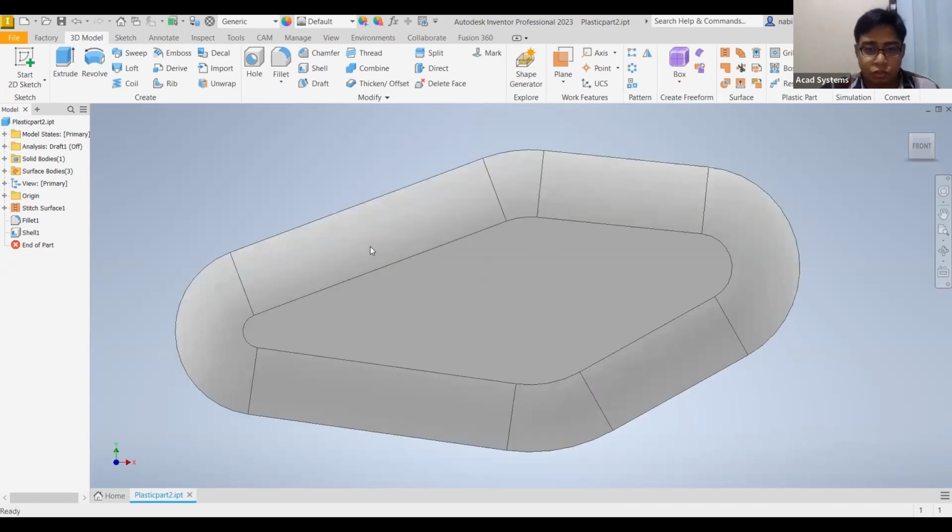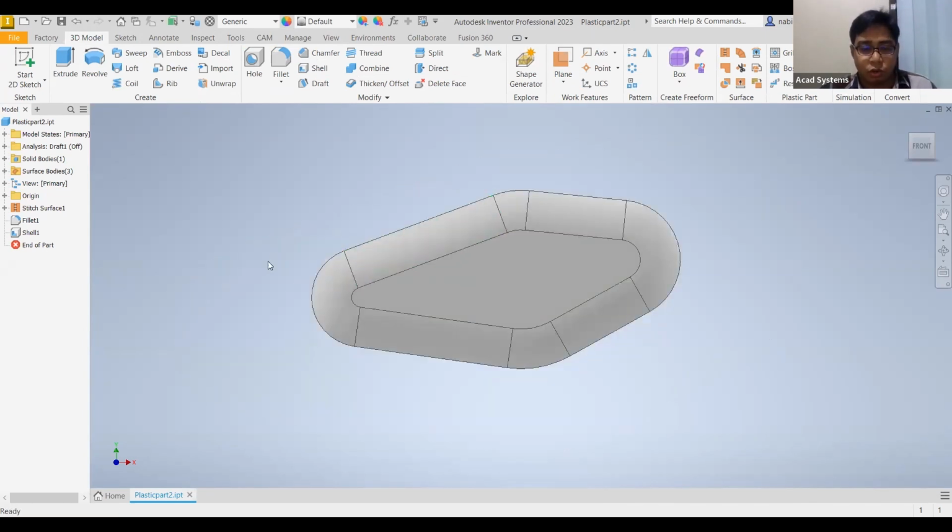Inside the mold base, you should have the core and cavity. So we're going to cut this into two, but we cannot just use straight cuts. If I try to cut something like this, for your core and cavity, you should have something like this. So you have core and cavity, and then you have the plastic part inside here. This is where we're going to put it. You cannot just cut like this because the top over here cannot be taken out later on. So you need to specify the cut section properly.